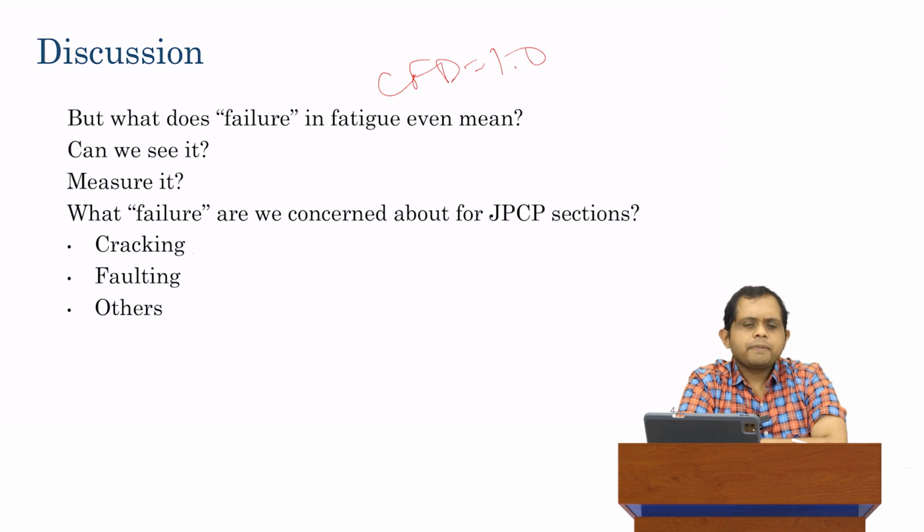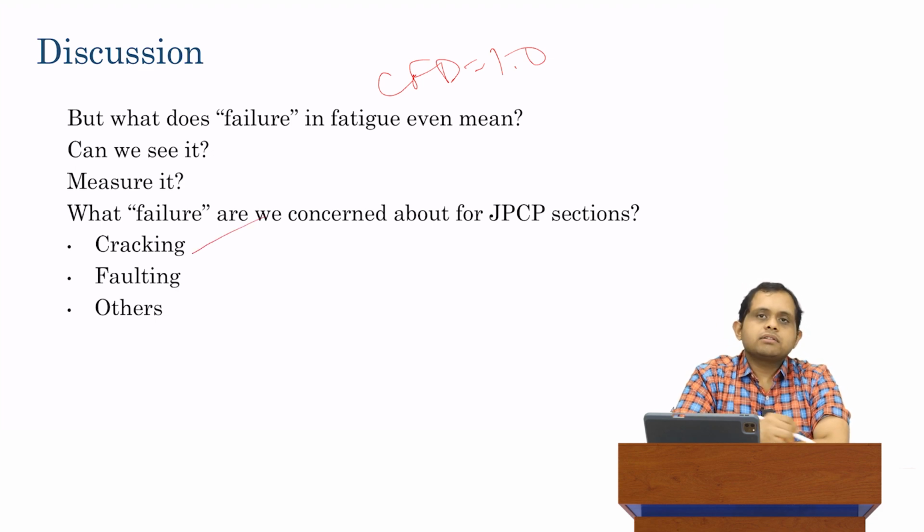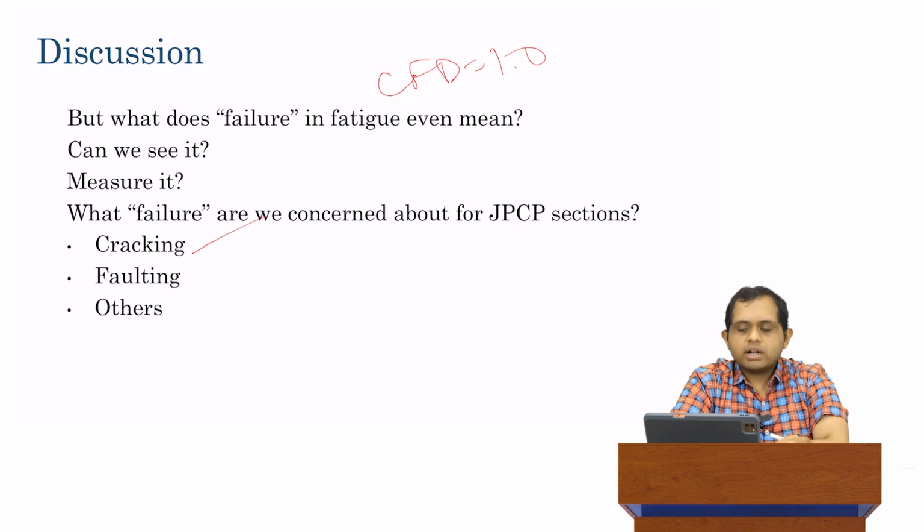You can't see it. Can I take out a scale? Can I put a ruler, or could I get a thermometer or something? Can I measure the fatigue damage in the field? No, not really. What can we measure, however, when we go out in the field? We can measure cracking. And if you go back to module 1 in our lecture 4, we did talk about how cracking can be quantified and how it's measured.